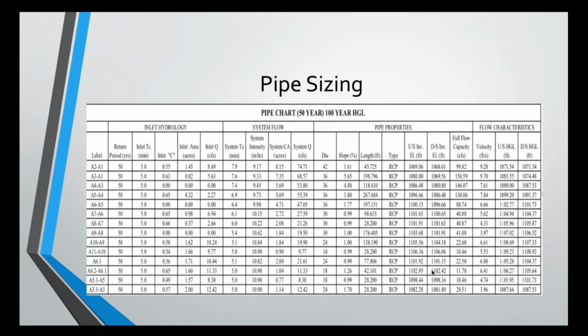Also, while creating the pipe network, the type of inlet and type of catch basins are chosen for the design. And a gutter spread is designed following the Forsyth County Unified Development Code.